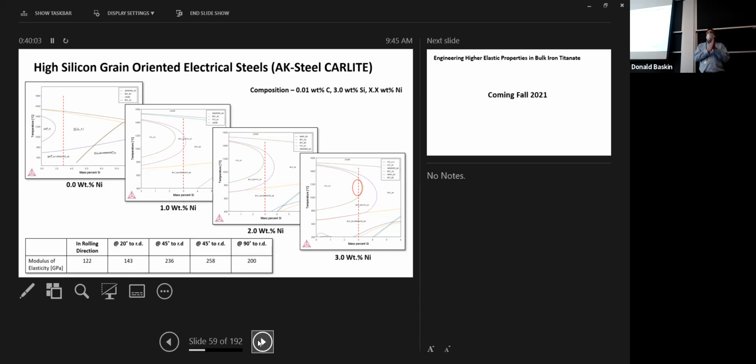Okay, if you took an electric motor, like the electric motor that's used on this window covering here, or the thing that pulls the projector background up, if you took that little motor apart, you find that there's little steel laminates in there. The little pieces of steel are cut with a die, so they all have the exact same shape. And then they somehow either bond those together or they rivet them together. This is very effective at focusing magnetic flux, which then makes your electric motor more efficient.